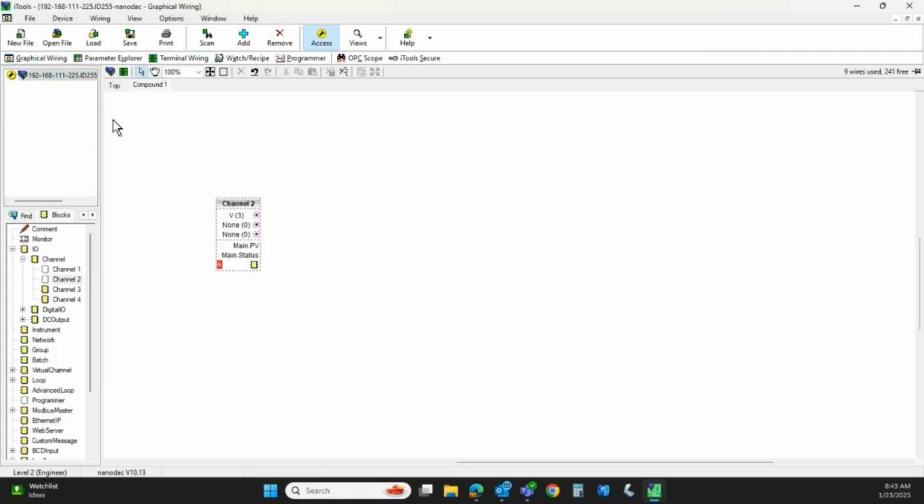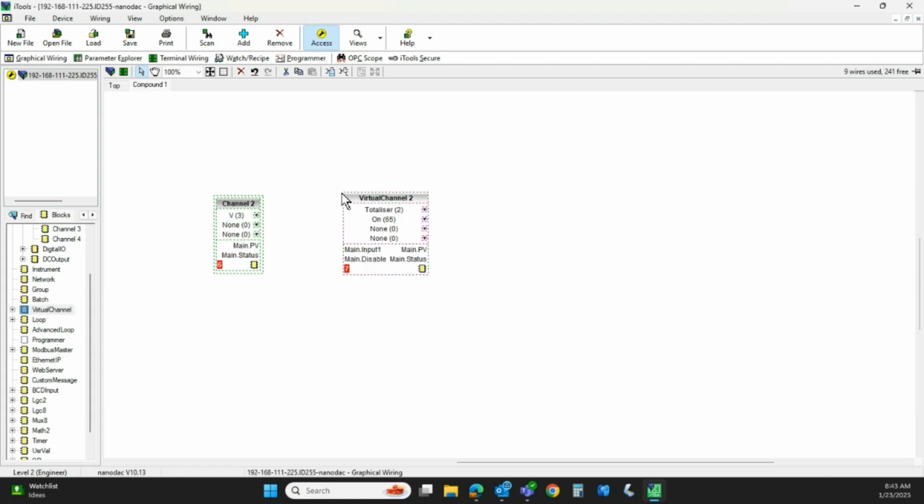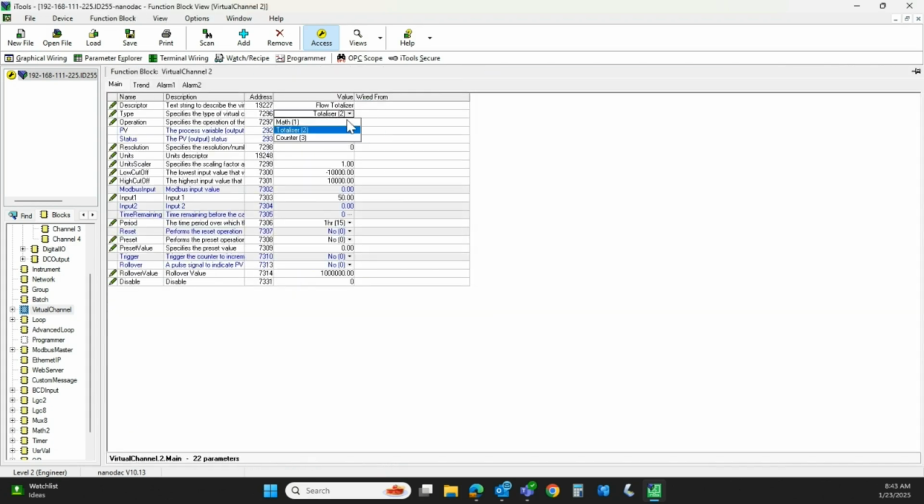We'll go back to our graphical wiring. What I want to do here is, this is great. It's going to show you flow, but it's not going to totalize it. So I'm going to come down here to what we call a virtual channel. I'm going to drag that channel out here, and we'll double click on the gray header. Now, by default, this is basically set up as a math. I've labeled it flow totalizer. We're going to select the totalizer function, and we're going to turn that on.